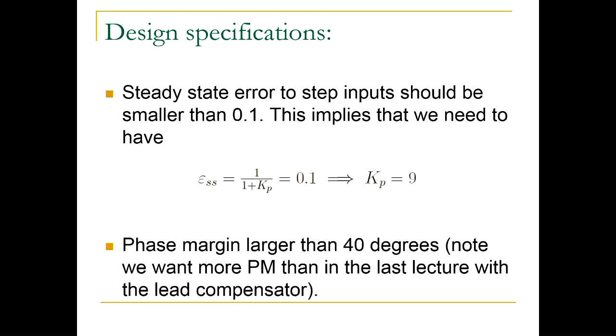And then we got a gain characteristic that looked like this, right? So then, obviously, this is not the full story. There was some phase characteristic as well, right? And that was going to cross minus 180 degrees at some point because we had 3 poles. Each of the poles would contribute minus 90 degrees. So eventually the phase would cross minus 180 degrees.